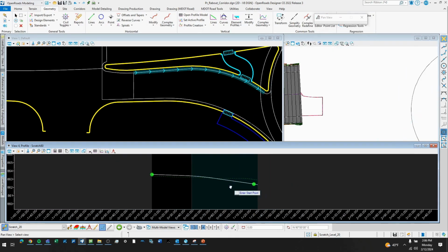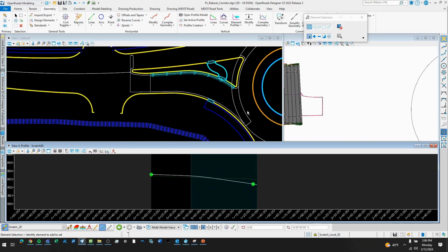I do prefer these to be coming up and in, just from a roundabout perspective, as this is going to be 1.5% perpendicular this way. Having this come in, going up at like 1 to 1.5% is going to be a little bit of a smoother transition.